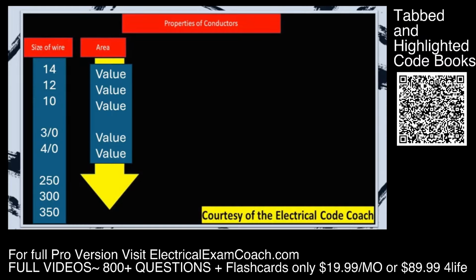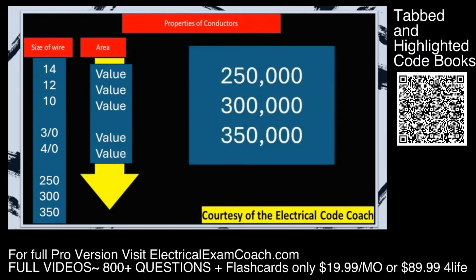You'll notice when you get down to 4/0 that the values stop. And the reason is because the left-hand side of this table, the 250, 300, and 350, are already showing you what the circular mils are in KC mils. So we have 250,000, 300,000, 350,000. So once you get past 4/0, you're going to get into 250, 300, 350, and all you have to do is add on the 3 zeros.